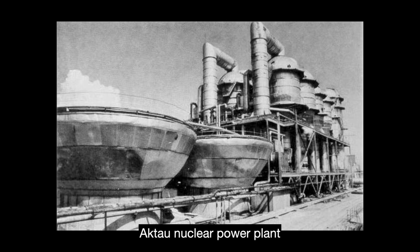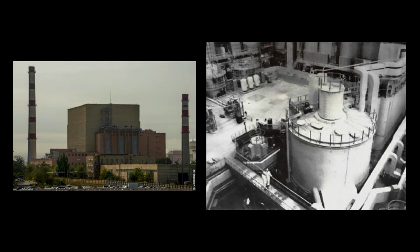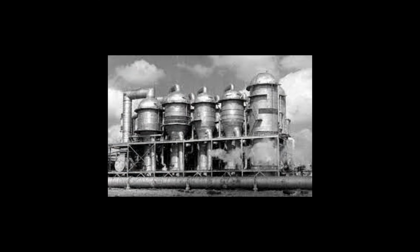In 1973, a sodium-cooled reactor, BN-350, on the east coast of the Caspian Sea provided electricity and nuclear heat to a desalination plant. Located just 12 kilometers from its host city, the reactor complemented a traditional coal-fired power plant. Its heat provided the energy for the first stage of an MED desalination system, the one that uses steam-filled heat tubes. The system worked fine for its lifetime with no reports of sodium leakages or abnormal operations. The reactor was shut down twice a year for scheduled maintenance.